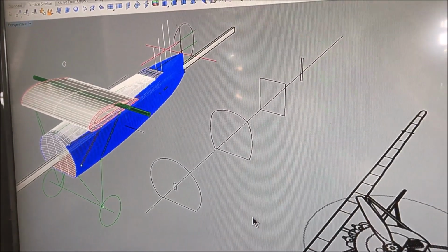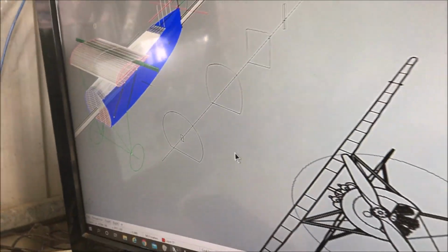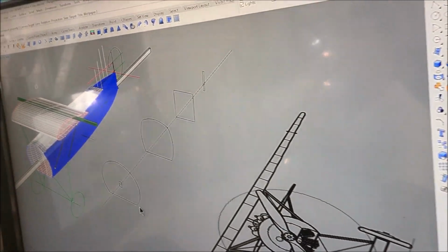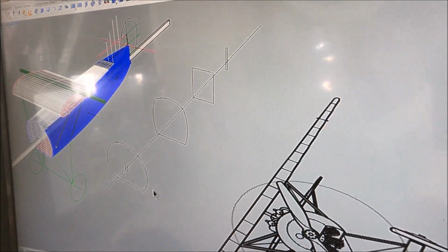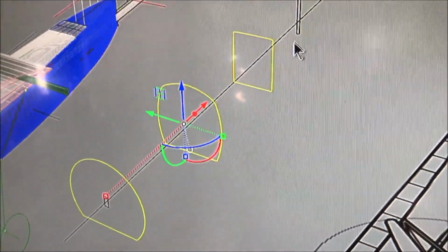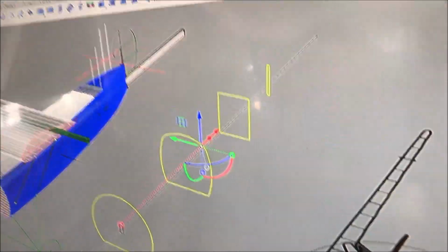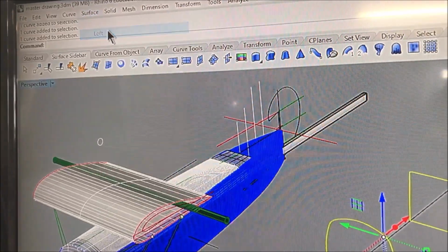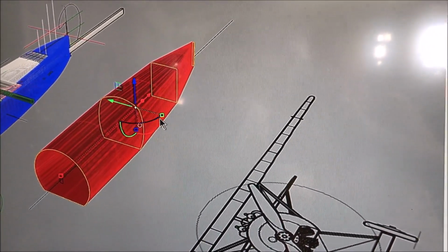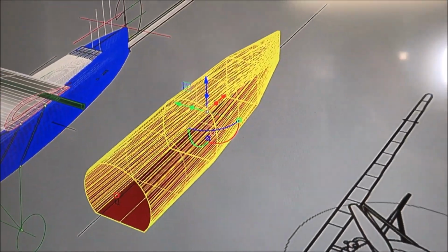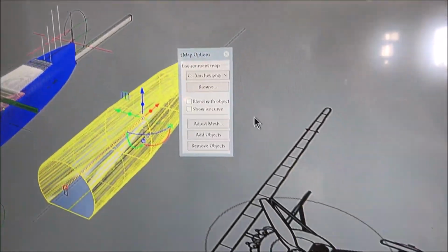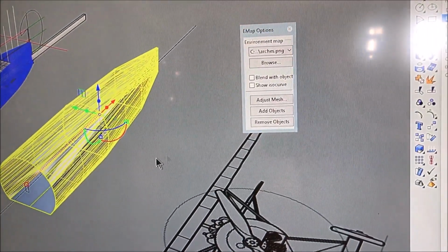The magic bit of this, there are obviously tricks and neater ways to, and refinements to do, but in essence, what you can do is select that curve, that curve, that curve, and that curve, and Rhino will loft them together. That's magic. Create a fuselage. You can make it pretty, go up and put a texture on it so you can see it a bit better maybe.